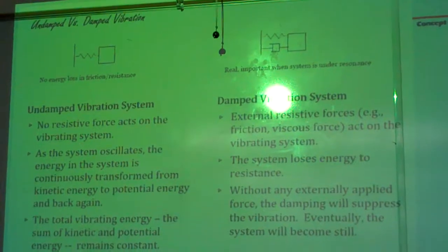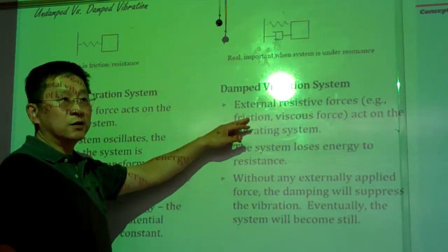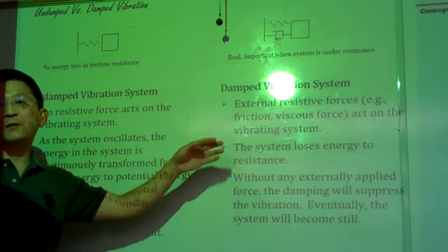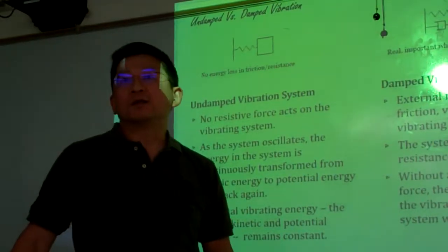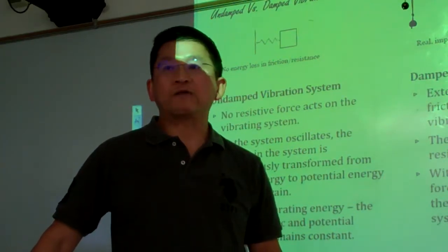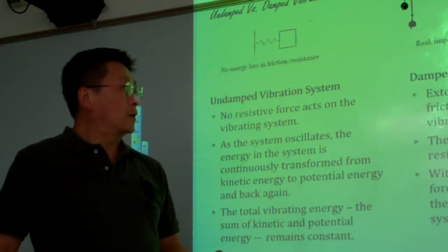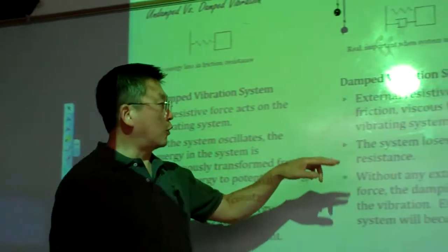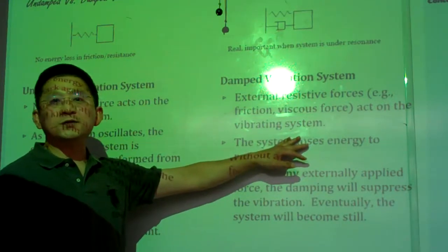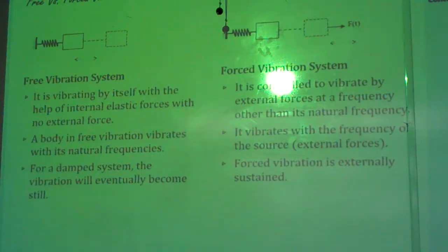For the damping, basically here we consider the damping is from friction. Friction has different types. We have viscous friction, so basically that's viscous damping. And we have dry friction, basically Coulomb friction. And we have more, and in this class, I'm going to only focus on viscous damping. Other nonlinear damping components I won't touch.